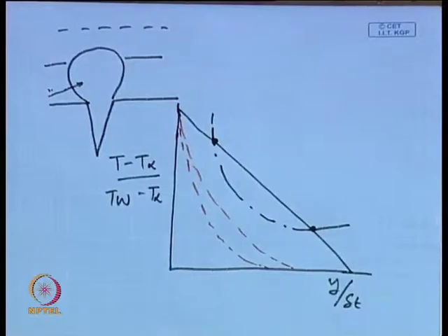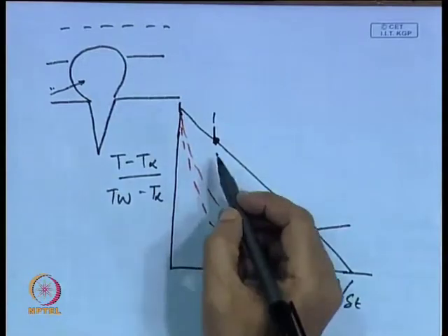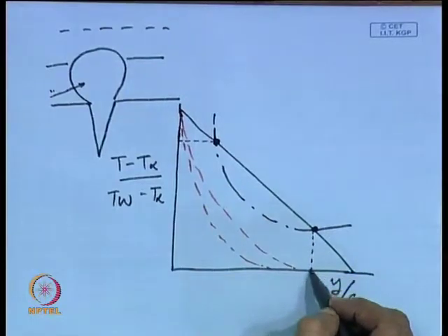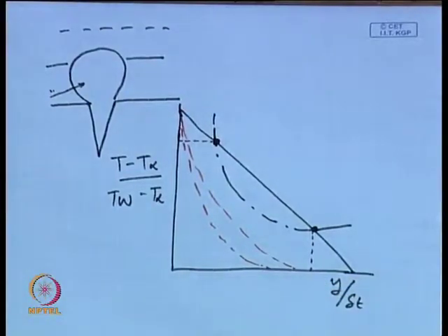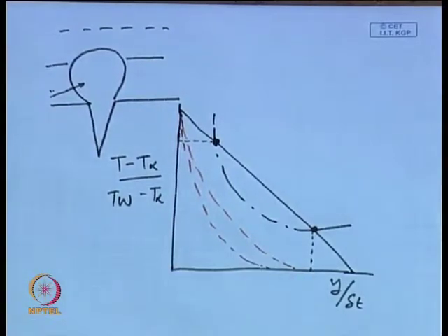So, if it is intersecting the steady state temperature at 2 different points, these two superheat values are very important. These two are the limiting superheat values. Corresponding to these values, we can also calculate the vapor nucleus radius. Those equations have already been given to you in our previous class.